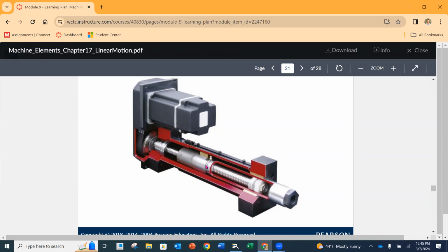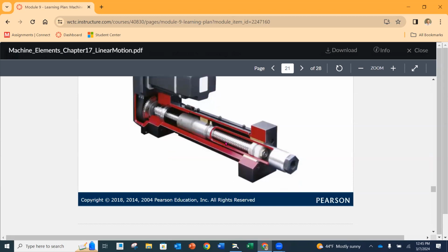Yeah, great point. So Ryan just brought up the fact that with screws, you get positioning accuracy, and it doesn't have to be the same increment. It doesn't have to be all the way one way or all the way the other. You can increment it at 1/4 inch, then an inch or whatever, and it's very repeatable and accurate, compared to cylinders, hydraulic or pneumatic.